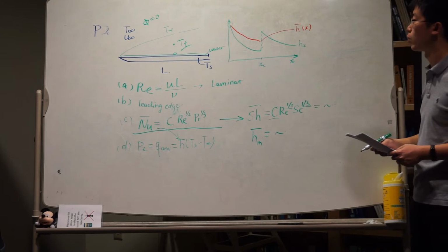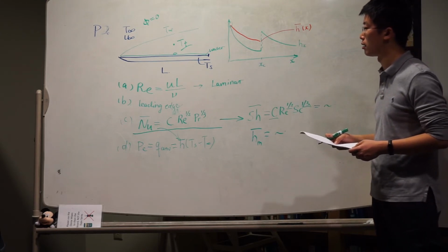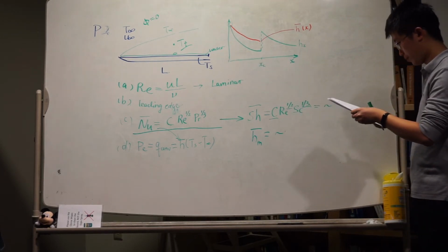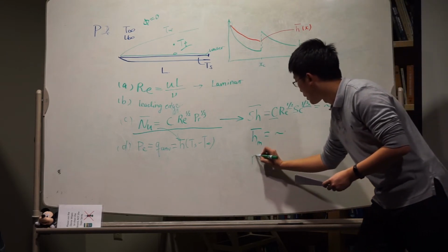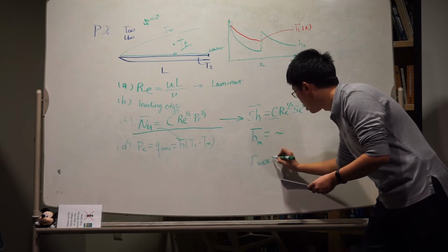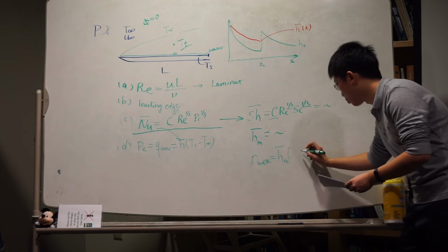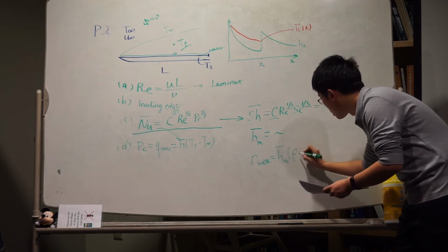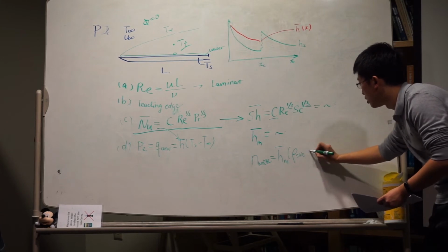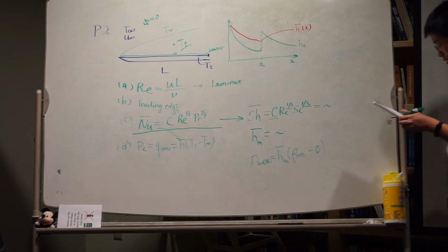The density of water vapor will be just the water vapor density at equilibrium at this temperature at atmospheric pressure. And now we can calculate the mass transfer rate of water, which has a very similar form to Newton's cooling law. This is the rho at the surface, which is the saturation value, and this one is 0 because it's dry air.